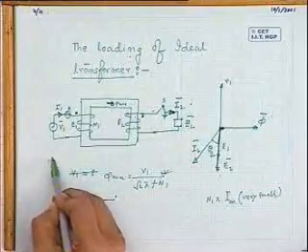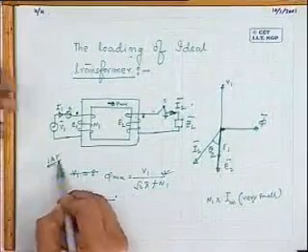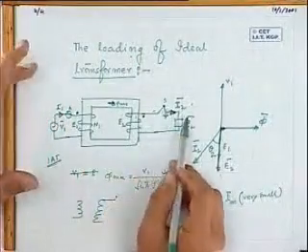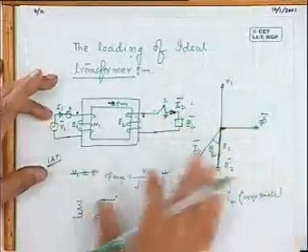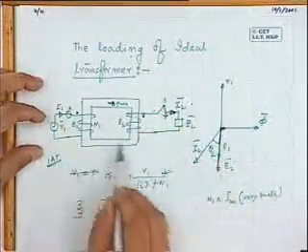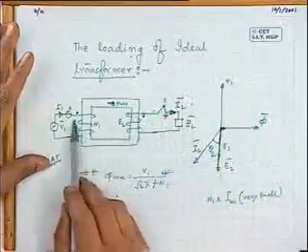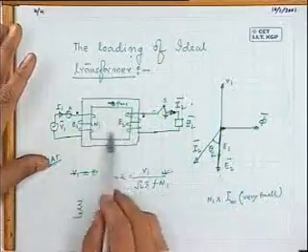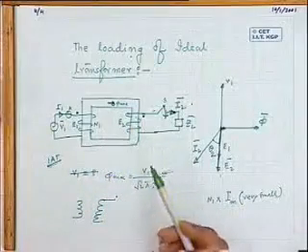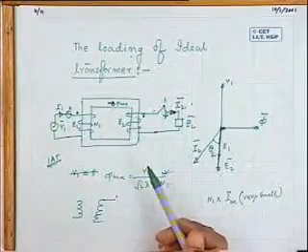Suppose the MMF necessary during no load condition was, to put it numerically, 1 ampere turn. I mean, some figure I am trying to tell. You have loaded the transformer. Some load current is supplied to the secondary. But after you have loaded the transformer, the total MMF acting in the circuit should be finally 1 ampere turn.